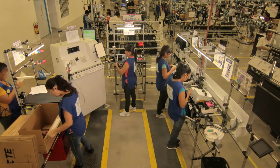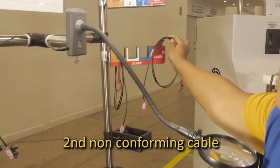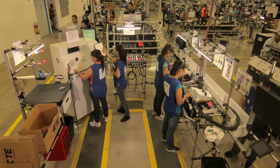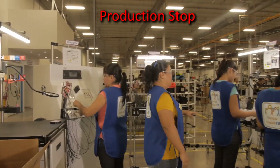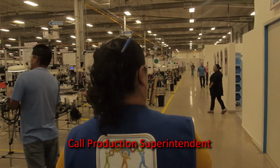When the second bad cable is identified by the electrical tester, information has to be recorded. The cable has to be placed in the second spot of the non-conforming rack. When the third cable is identified by the electrical tester, production is stopped and the production supervisor has to be called for immediate support and root cause investigation.